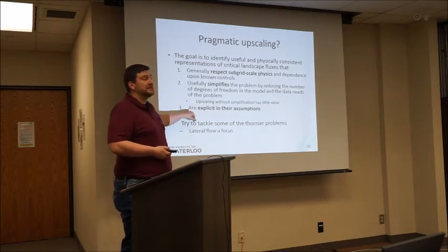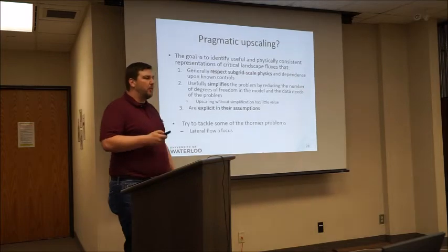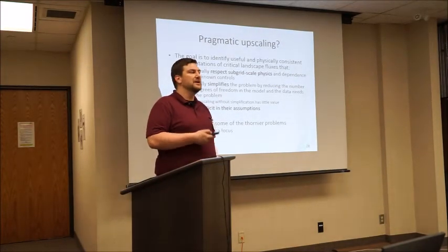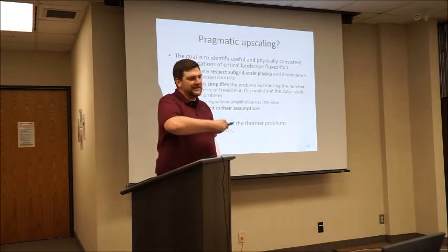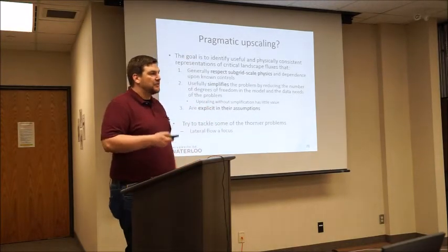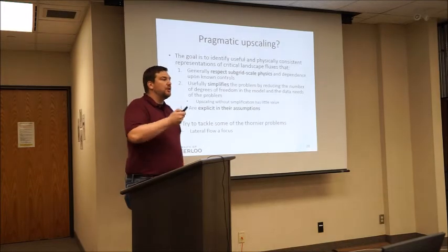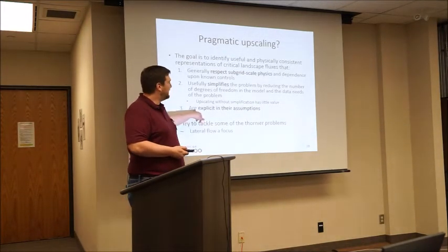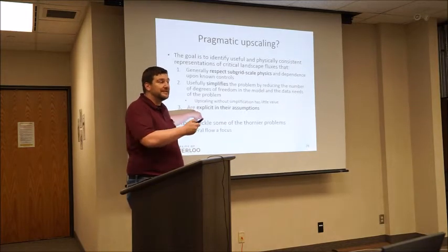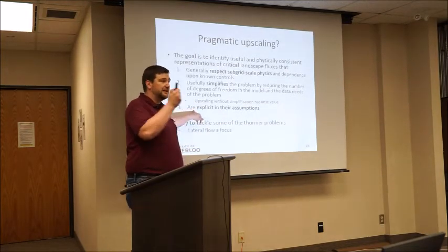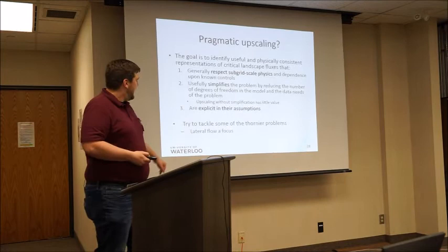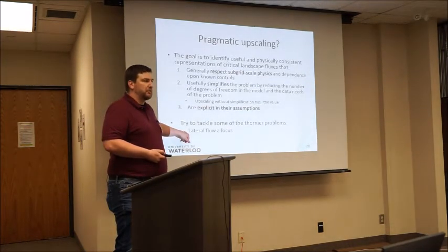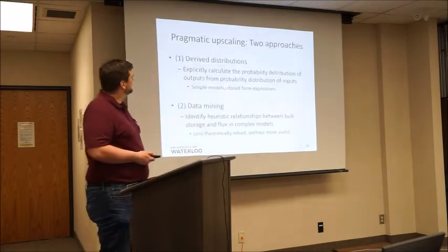And we want to be explicit in our assumptions. I want to understand, why can we get away with a power law description of infiltration in the Sacramento model and all these things? There's a reason why they're getting away with it. There's a reason why the system scales in that way. What is it? Let's find out what those assumptions are that are required to get you from the micro scale to the macro scale. And I'm trying to spend some time looking at lateral flow because that's a particularly thorny problem in these upscaling approaches.